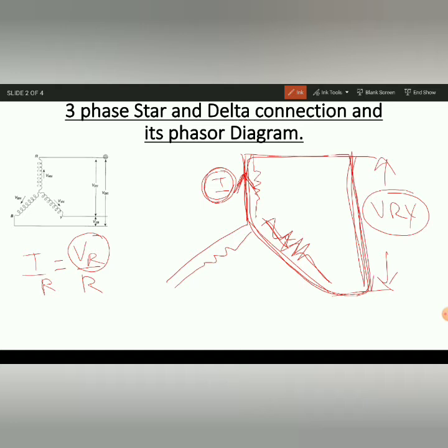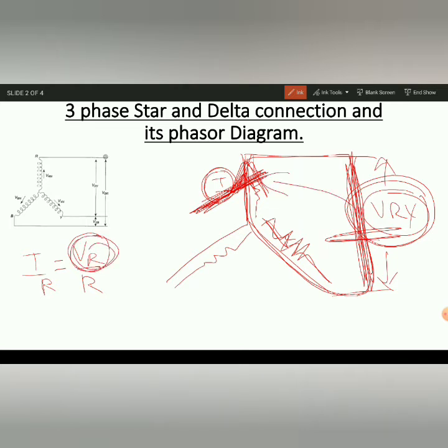So I can't use this line voltage for finding the current in only this wire. That's the reason if I know the line voltage, first I have to convert it to phase voltage, and only then can I apply it here. Then the current I find is the current in this particular phase. So it is vice versa.